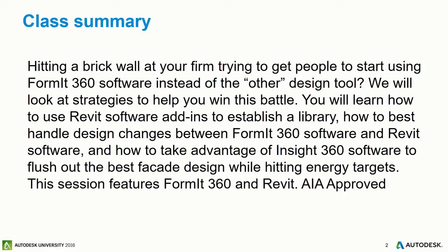The idea is I'm trying to show you a bigger picture of all the different things that would help you, either modeling-wise or implementing-wise, and understand how it interacts with SketchUp very well. Anything that's done in SketchUp can be brought into FormIt, and the big thing too is that FormIt goes into Revit. There's no throwaway. And the other thing I want to make sure everybody understands is groups are king. Groups turn into families. You can do all kinds of cool things with this workflow.